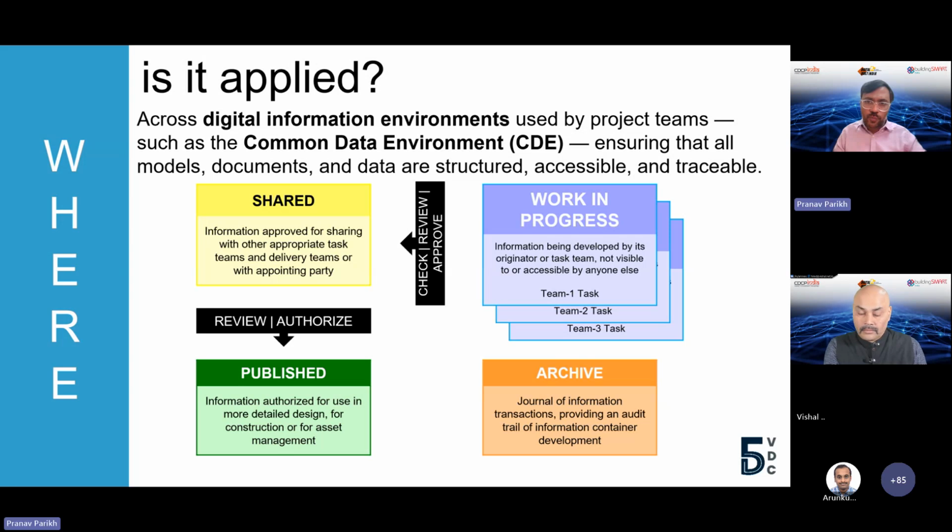A small point that I also want to put across here. All of us who have probably not implemented ISO 19650 so far may have done something similar as a DMS, a document management system. So we may be very much used to the concept of a document management system in terms of folder structuring. A CDE looks very similar to a DMS, but DMS and CDE are two completely different things. DMS is more about storing the files in an organized way and sending them for review. The common data environment, per the ISO 19650 guideline, is more about collaborating in one space. So both things are a little different, right?